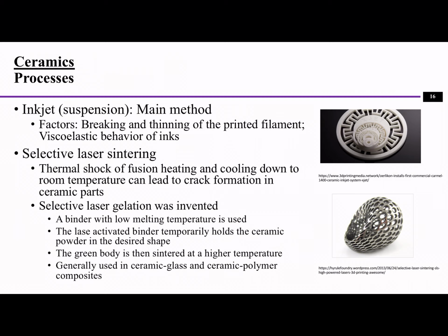And a common process is inkjet. Inkjet is the main method of creating ceramic parts, but there are breaking and thinning issues related to the printed filament. And also the viscoelastic behavior of the inks will affect the printing quality.